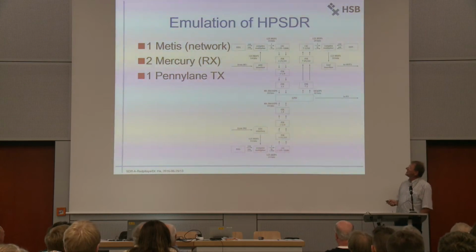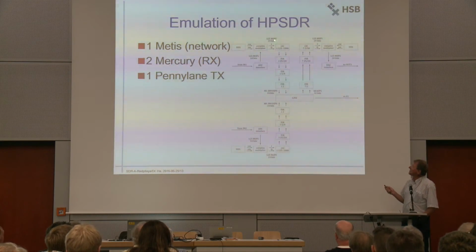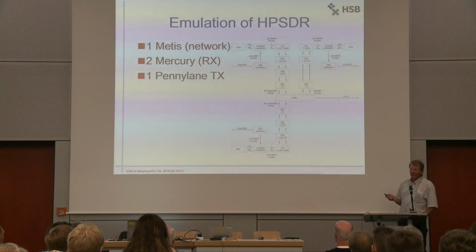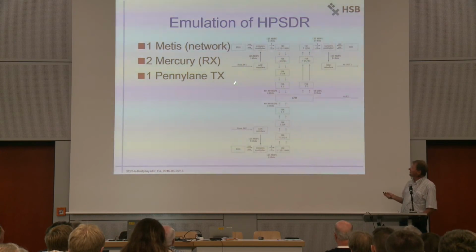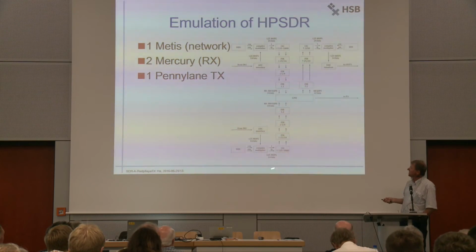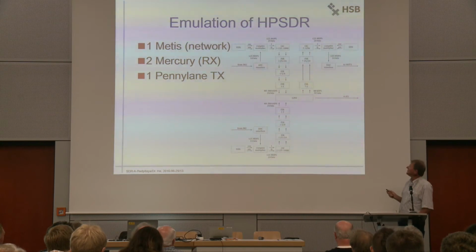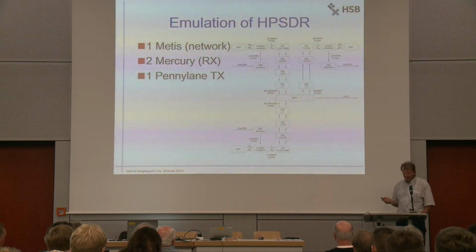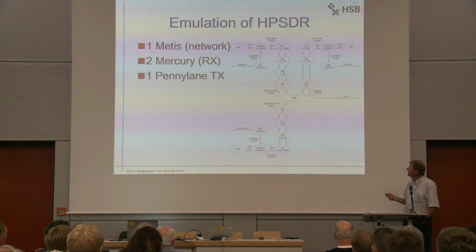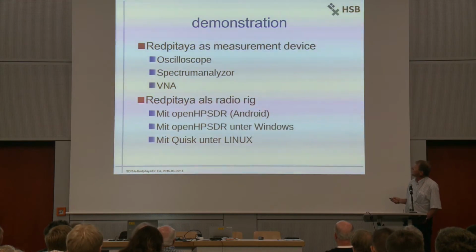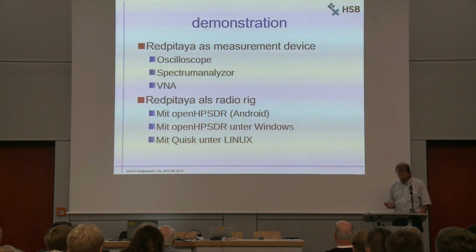Okay, this is the next step, the HPSDR emulation in the Red Pitaya, done by this circuit diagram. You see two receivers here, as we need only two receivers for the HPSDR. And this is a transceiver part, and here you see the CPU. It's from Pavel Demin's website. And let us have a little demonstration now.